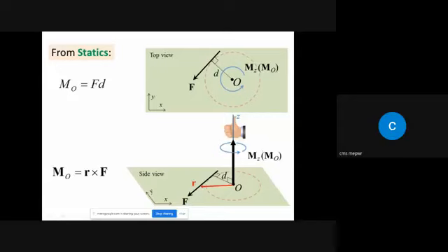If you remember what we studied in our statics course, the moment of a force is the rotational effect caused by the force about a reference point, or about an axis that passes through some reference point. In scalar form, the moment is calculated by the magnitude of force multiplied by the moment arm, which is the perpendicular distance from the reference point to the line of action of force.